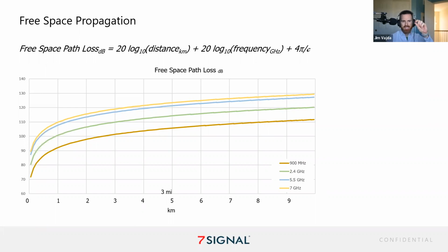The antennas are really tiny, particularly like 60 gigahertz. So you could have an array of 64 antennas all receiving the same signal and combining it and using DSP to make up for some of that loss. But definitely an important point that's often overlooked about receive aperture.